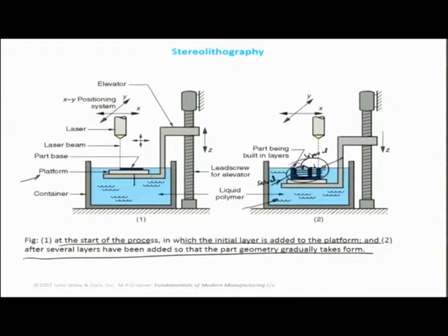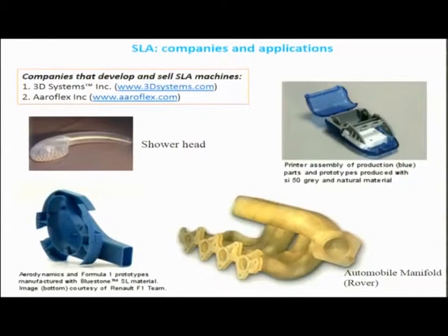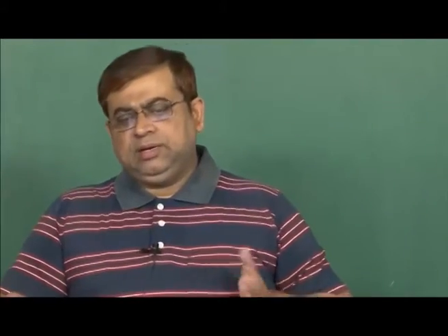If I look at what this resist was and how it would behave, there are many details which I have covered in my past lectures, particularly when we were talking about MEMS based sensors, where we detailed how there can be classification into positive resist and negative resist, and the chemical principle behind a weak acid liberating protons so that it participates and cross bonds, creates a three-dimensional network of bonds, and then you could remove the areas which are not bonded so well, which results in a solid structure.